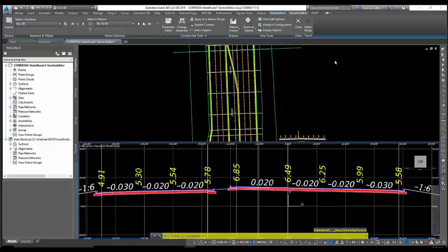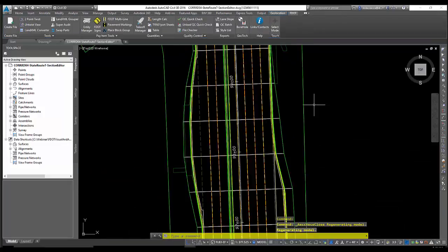So go ahead and click cancel, and to exit out of this file, just like the drive tool, never come in here and just click file close, because when you go to open up the file, your view might be reoriented to something different, and sometimes it's a little difficult to get your view back in top plan view. So always try to remember to come up here and click close to take you out of the section editor command.